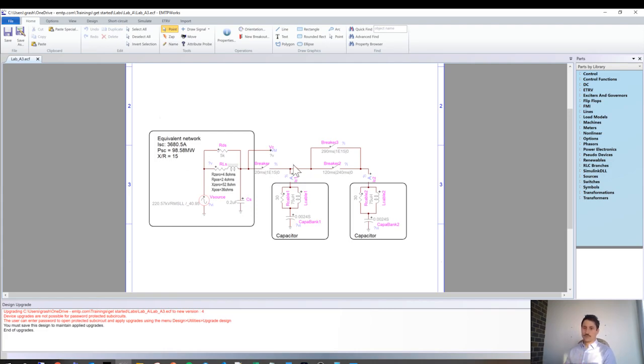Typically, to reduce those frequencies and current, you will add tuning inductances in series with those capacitors. Basically you increase the inductance of this circuit, and so you will have lower frequency and lower voltage and current magnitude, mostly current magnitude.